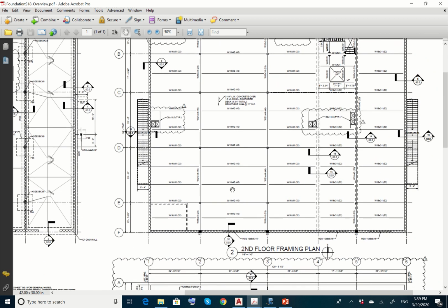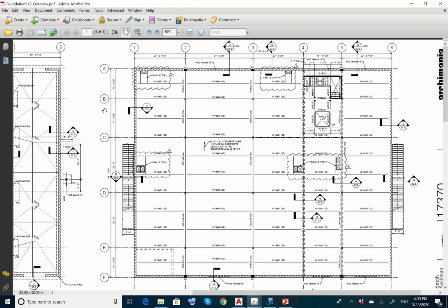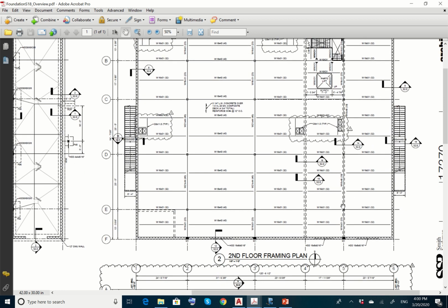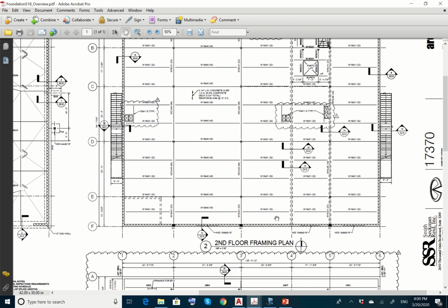Now let's go to the second floor framing. Now, in the model space, you're just going to be drawing all of those on top of each other. You're not going to be drawing this as another drawing, because you have already given the dimensions, the center lines, the labels for the center lines, and the CMU units, you drew the CMU walls over here. There is no reason to repeat that again. So you would just fill the CMU units to close the openings that were there.